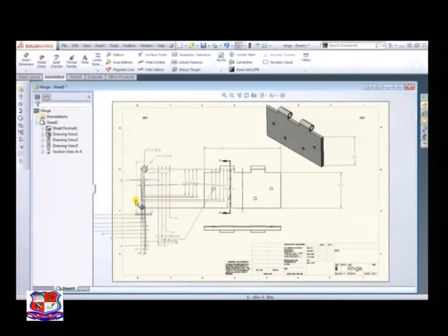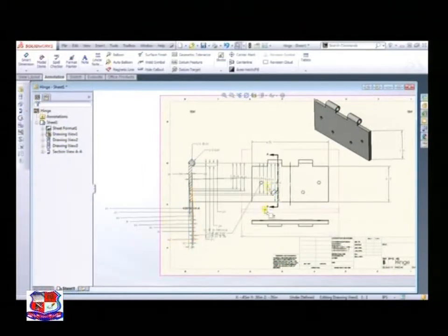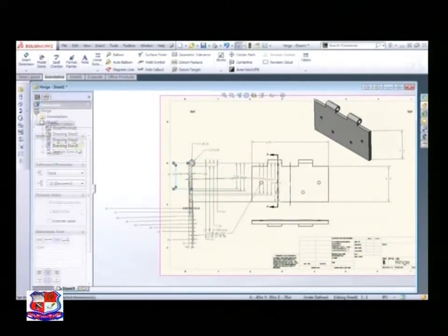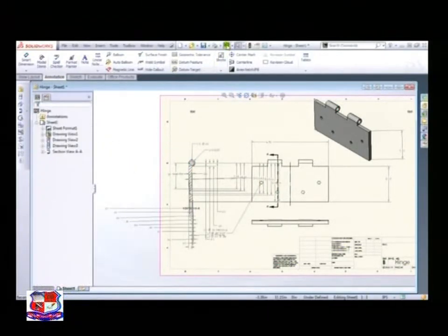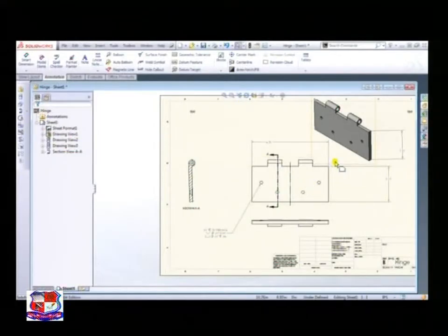And as you can see, SolidWorks will give us every dimension for that one part, but it also makes too many dimensions sometimes. So this can be helpful if your part is very simple, or if you want to make sure you do get all the dimensions. But sometimes you'll have to just clean them up, move them around a bit so they don't look as cluttered. I'll go ahead and just hit undo a few times to undo this, because for me it was a bit